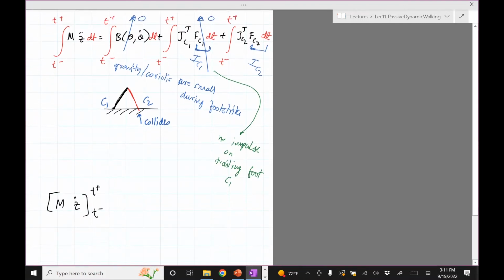Turns out that m, if you remember, is only a function of angles, theta, and is not a function of velocity. During collisions, all the angles don't suddenly change. The velocity does change, like the bouncing ball, but the angles don't change. So I can assume that m, which is only a function of theta, is constant during collision. In other words, the angles won't change abruptly, though the velocity does. And that's why I can justify taking m as a constant and then integrating only the acceleration. Okay, so this is equal to